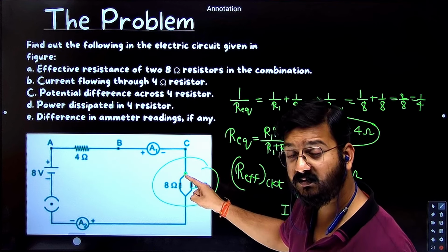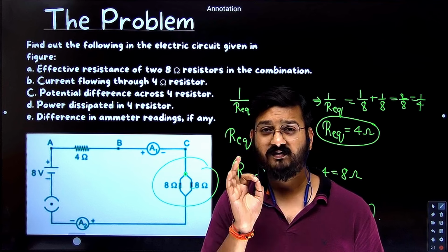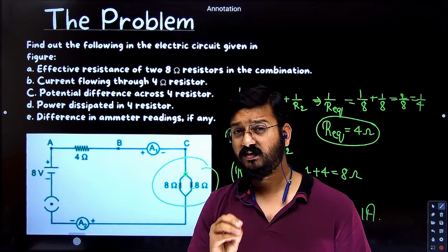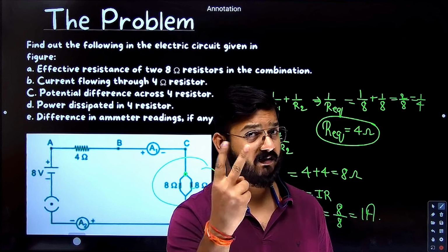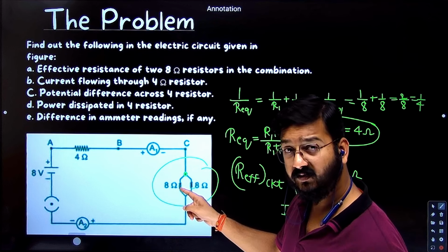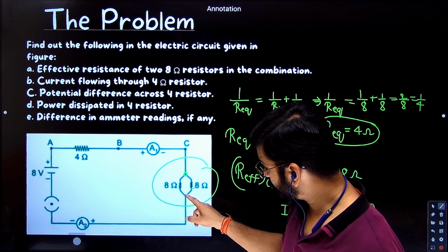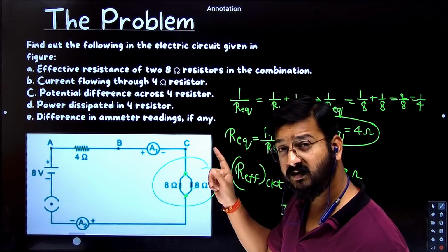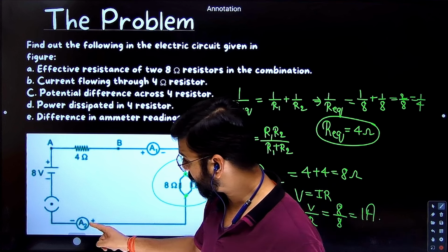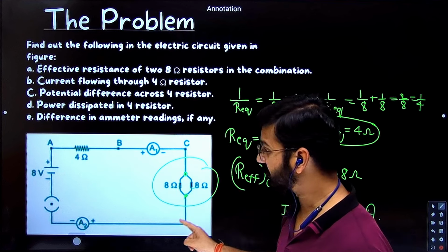Now the same current will flow, reach to this point. When it reaches to this point, it has two possible paths. And if you see, both the paths have same resistance. So current will get divided into two equal parts. So how much current will go into this? 1 by 2, and this also 1 by 2. 1 by 2 and 1 by 2 will meet here. What is 1 by 2 plus 1 by 2? 1. So 1 ampere will again flow through A2 and then it completes a cycle.